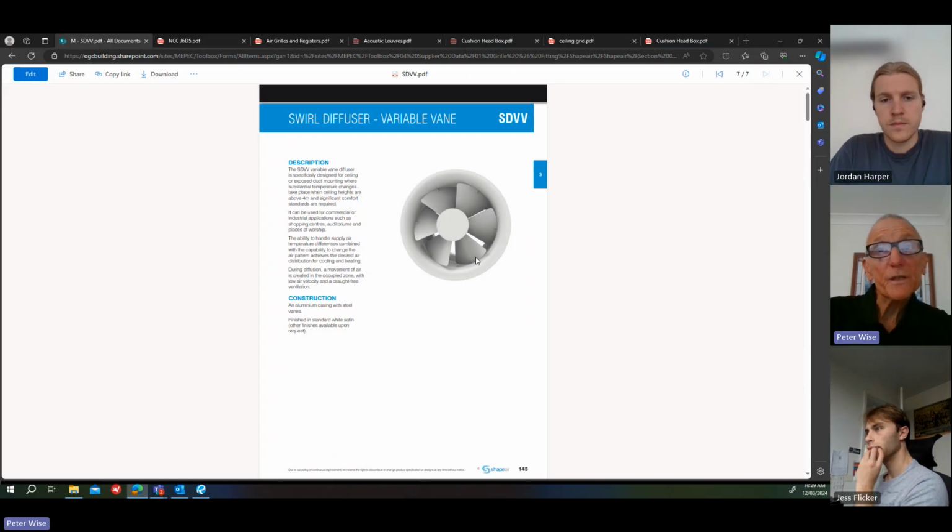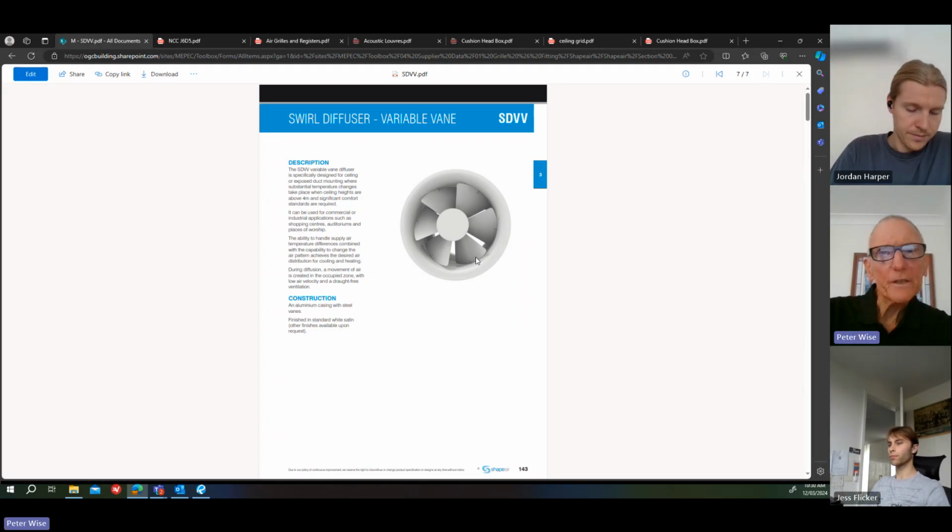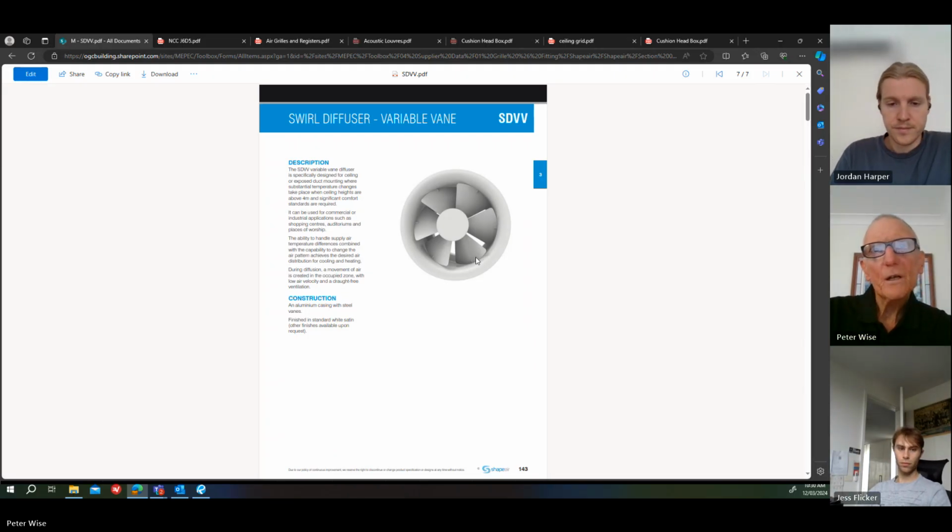But we used these in that museum, the same project. We had an exhibition hall, which was 8 metres high. The temperature restrictions were plus or minus 0.1 of a degree. Humidity, and I don't know whether you know how hard that is to achieve, but it's not easy. Humidity is even harder to achieve. They wanted plus or minus 2% relative humidity. So we had to get very, very good air distribution, and the controls were very expensive as well.